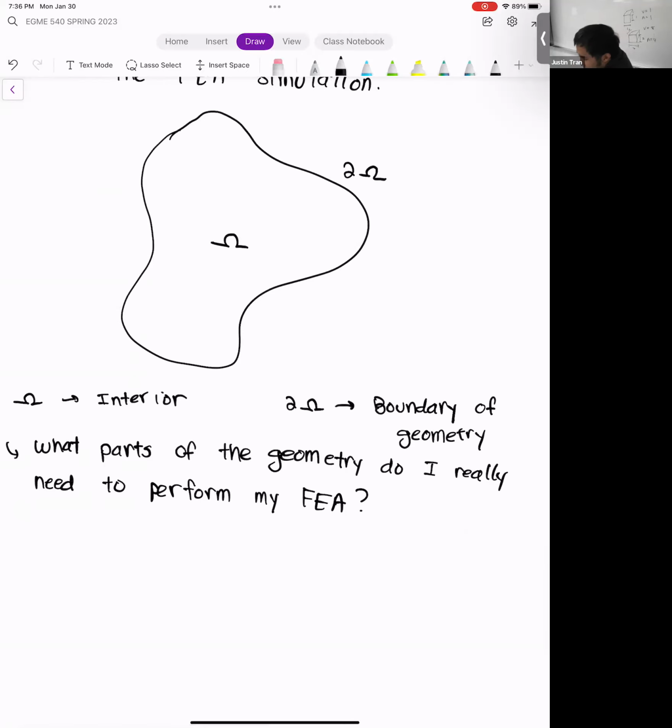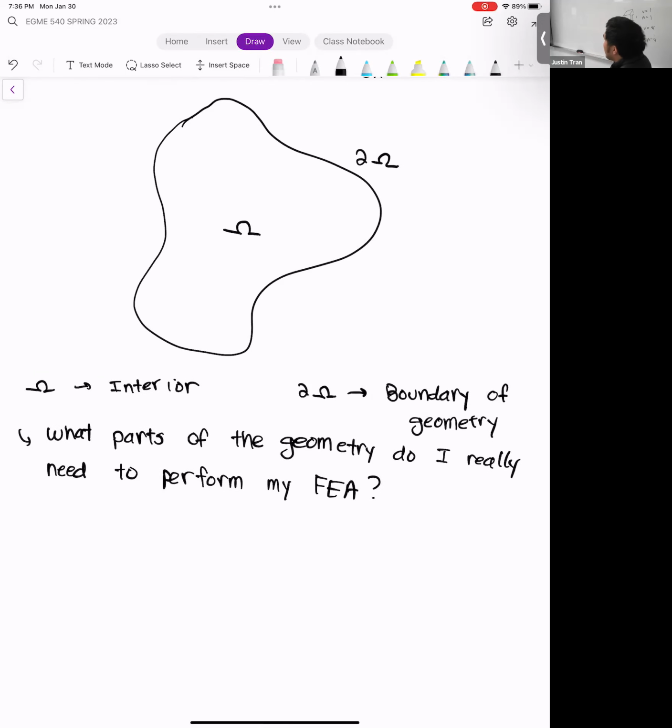This is something I go through a lot with my undergrads doing finite elements. A lot of them are working on situations like this, with undergraduate projects like Titan Rover, or Formula, or Baja. They have other students producing the CAD files, and those CAD files are produced mostly so that students can actually construct whatever project they're doing. But a lot of times those CAD files are way too complicated to use for FEA, where the FEA should really be focused on just a small part of the geometry.